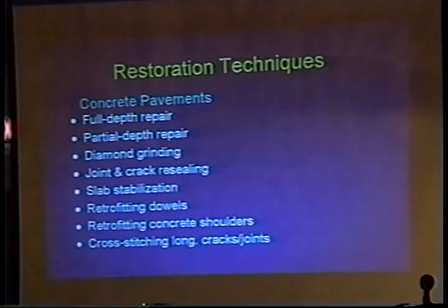While it's still in a relatively young life, 5, 8 years, and in reasonably good condition, you can widen those shoulders with concrete, tie them into the existing pavement, and keep the joints in the same location as the pavement. That will also help spread the load as trucks go over onto those edges of the concrete pavement.